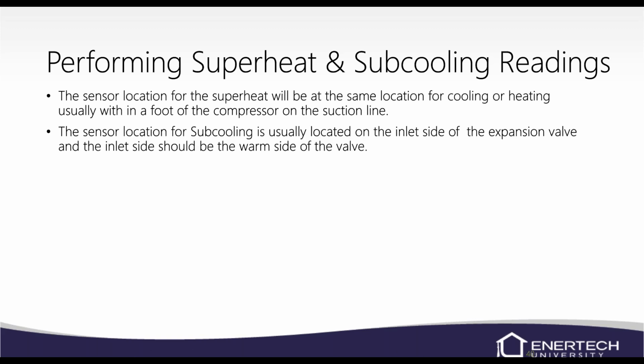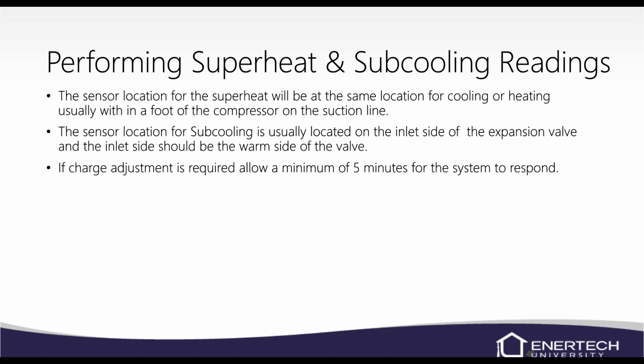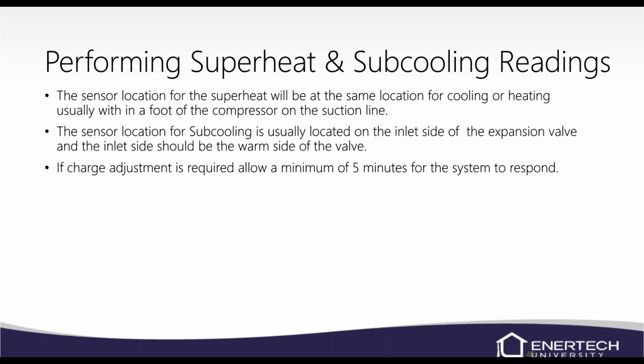Subcooling, it's the inlet side of the expansion valve, and the easiest way to know is it's the warm side of the valve. If charge adjustments are required, you got to take refrigerant out or put refrigerant in. Put some refrigerant in, wait about 5 minutes, and let it balance out a little bit, and then check your readings again.